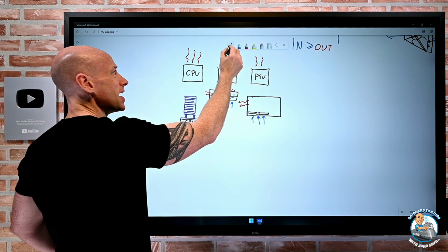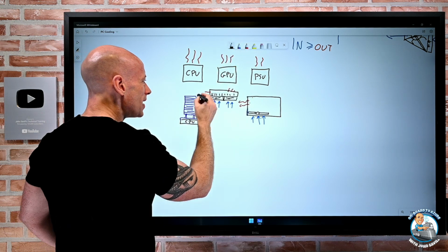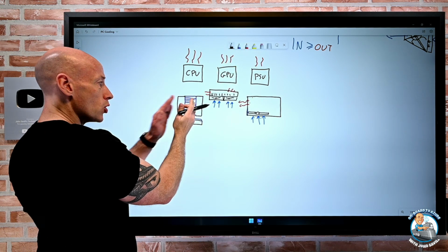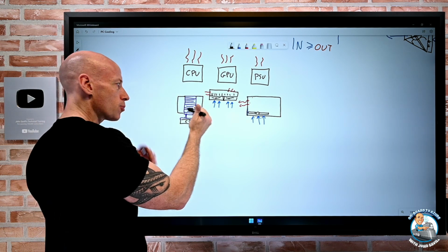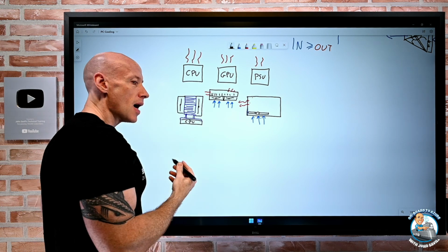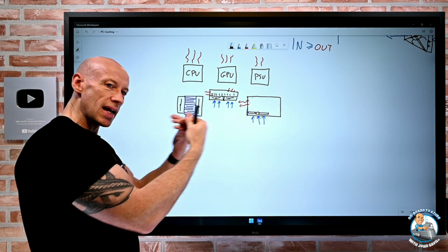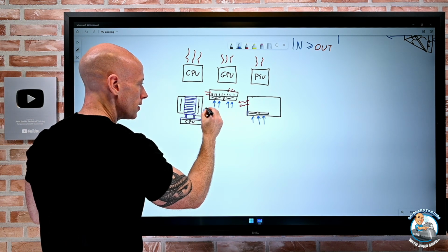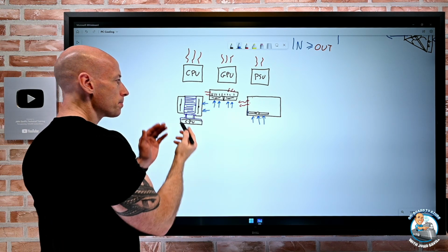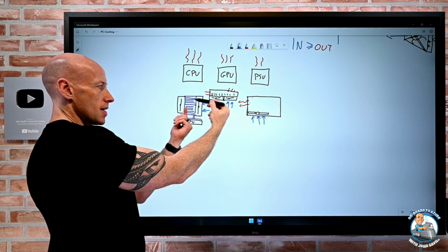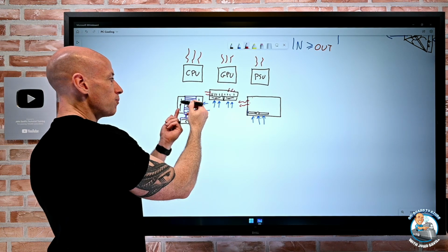And then what you attach to this typically is 2 fans. Now there are different designs. There might be designs where it's actually 2 sets of fins and the fans spread out. But the whole point is you've got fans here, and I want them to flow in the same direction. So for example, this fan would be intaking here, so that cold air is being blown over those heat sinks, and then this is blowing in the same direction.